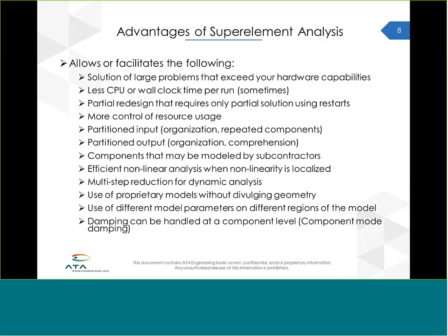If you know the damping characteristics, again, from a modal test for, let's say, the satellite, and you're coupling that satellite to a launch vehicle, using superelements, you can preserve those damping characteristics and say, here's the damping on the satellite, but solve the whole system of the satellite plus the launch vehicle.